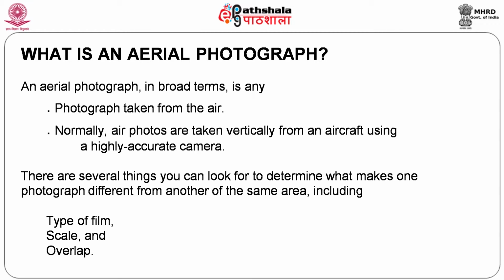Now, we have different types of photographs. But before that, let me tell you the importance. Previously, for a long time, photographs were taken using normal films. Of course, exclusive films were meant for that. They are film based, and the most important concept in aerial photography is the scale of the photograph or the overlap of the photograph. To what extent is the scale? When I am taking a satellite image, I do not bother with the scale. But when I am taking an aerial photograph, or photographing the surface from the air, I have an issue, namely the scale factor.